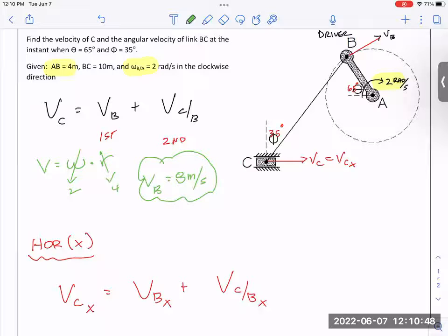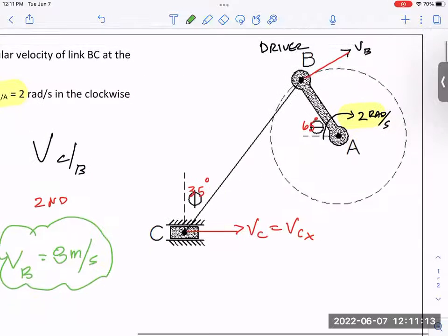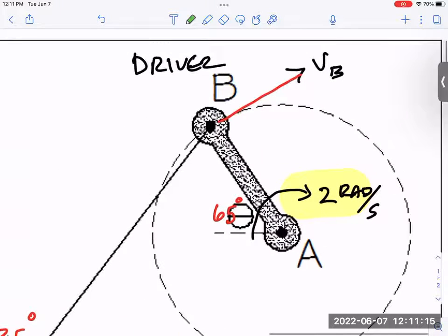Now, stare at the units. Angular velocity is radians per second. The 4 was meters, right? So meters times radians per second is meter radians per second, but because radians don't exist, that's meters per second. So we actually know the velocity of B. Now, unfortunately, is that going in the X direction up there? No, but let's get a little more creative.